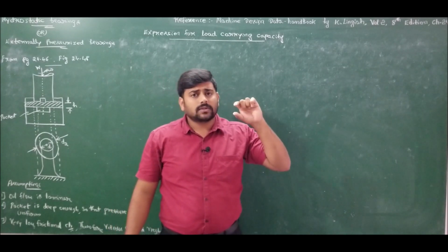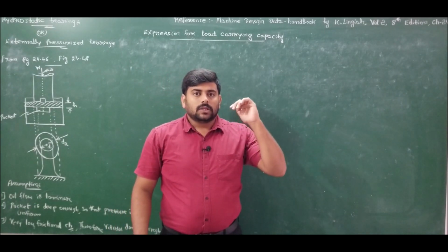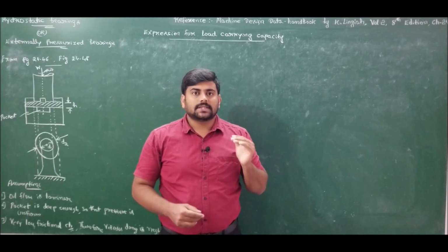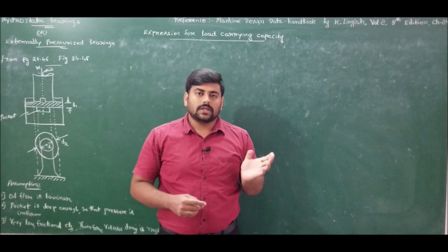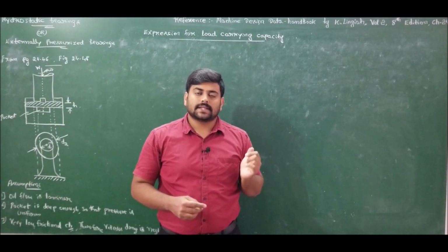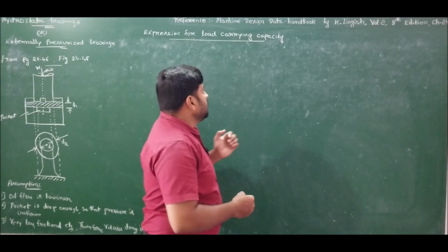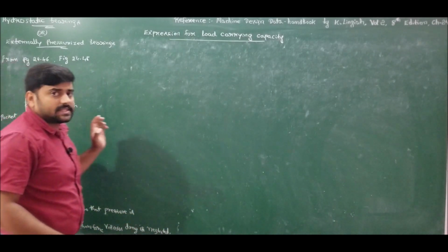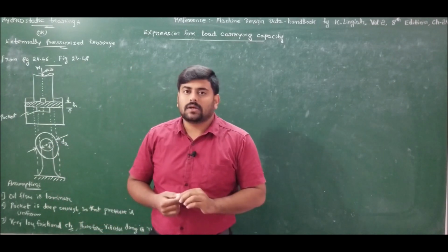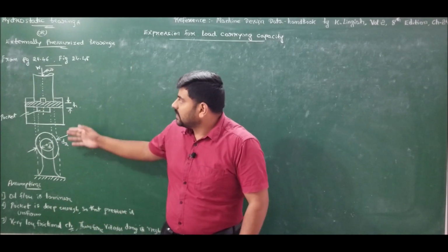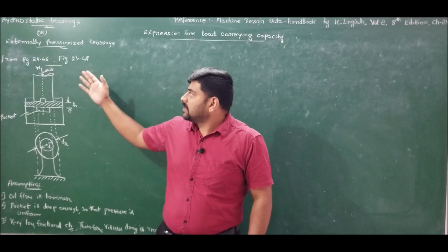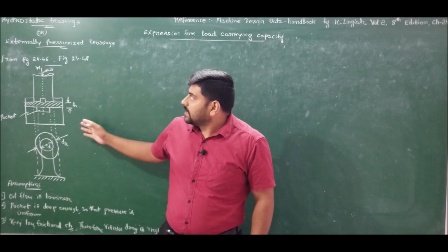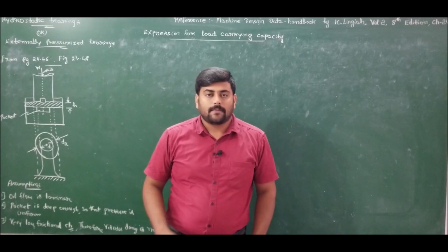In the case of hydrostatic step bearings, the load acting on the journal or the shaft will be withstood with the help of pressurized oil, which will be pressurized with the use of external accessories such as a pump. Now the inlet pressure, which is nothing but the pocket pressure, helps us to withstand the externally acting load on the journal or the shaft. This figure is available in our data handbook. If you refer to page number 24.46, figure 24.48, you will get the diagrammatic representation of the hydrostatic step bearing.